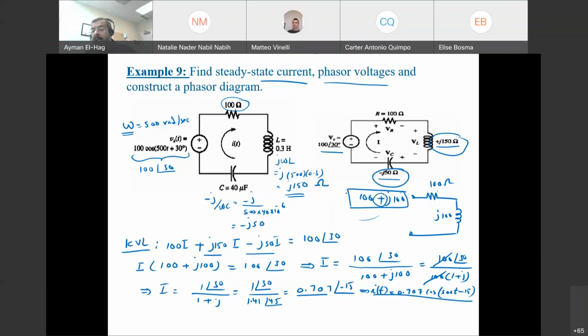If the sign is positive, then the inductive part is the dominant part, because the positive was more than the negative, so they cancel, as if the capacitive doesn't exist at all after reducing a little bit of the inductor. If this sign was minus, then this whole overall circuit we call a capacitive circuit, because the capacitive component is dominant in this circuit. So this is something very important to notice.